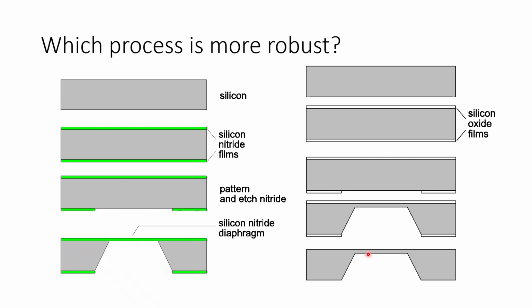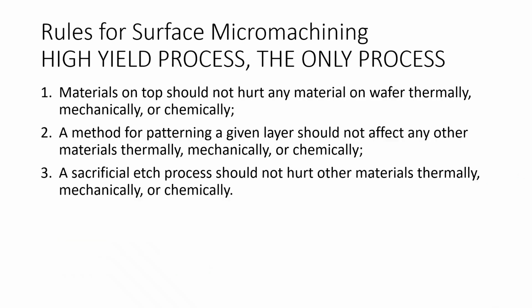Whereas in this device, if you want to put piezo resistors, you might be able to just dope it, and it would have a higher piezo resistance sensitivity. So there you go. You have different pros and cons. Very rarely do you have one material system, one design, one fabrication process that's favorable in every aspect.